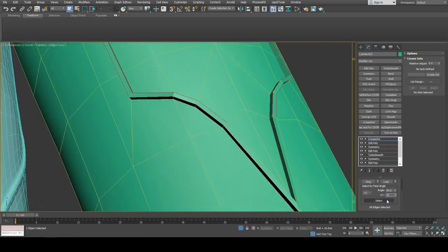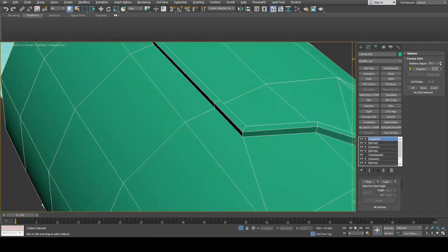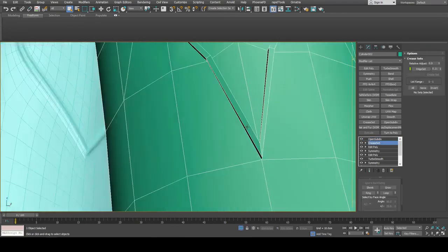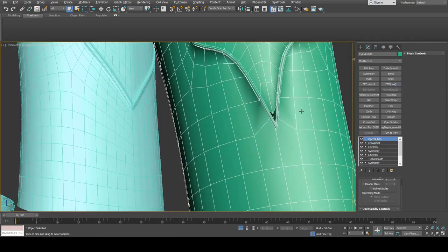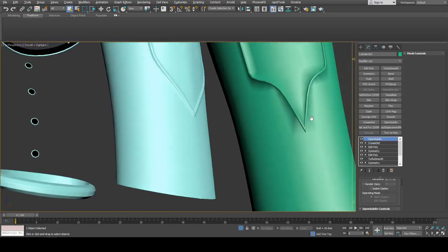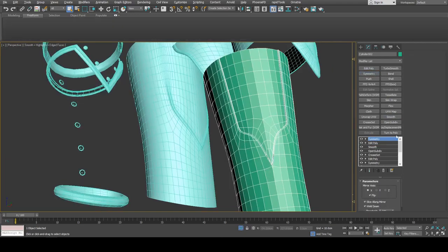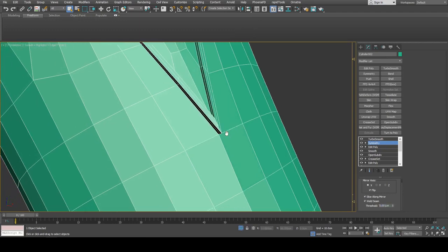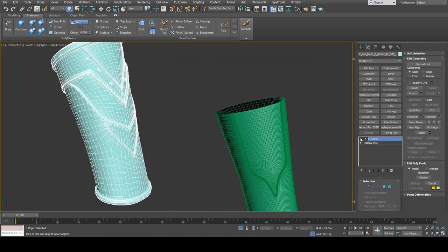Alright, I'm just going to make sure these are the correct edges. Maybe increase this value. And then open subdiv, and here is our crease happening here. I can, for example, crease this just to make it sharp if I want it to be sharp in the middle here. Alright, and there we go. Now we have our crease detail like this. I'm going to go ahead and decrease the threshold to 0.001 just so that I don't get that wadding effect. Alright, there we go. Alright, so now for the rest of these objects, we can just model them one by one.